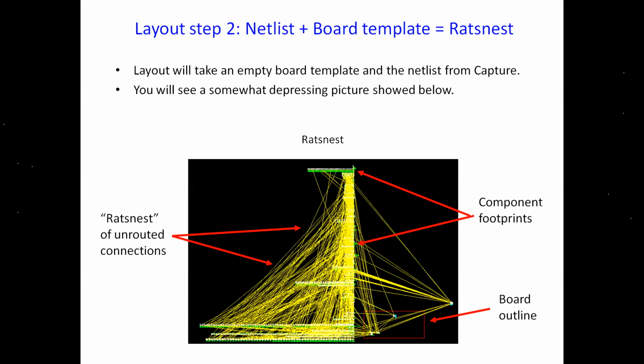After making the connections, after making the schematic layout and after checking, you will have to translate all the information, that is the circuit information, to the PCB editor by a simple click of a button in the EDA tool. Prior to that, you have already created the footprints of all the components involved in the circuit, right?